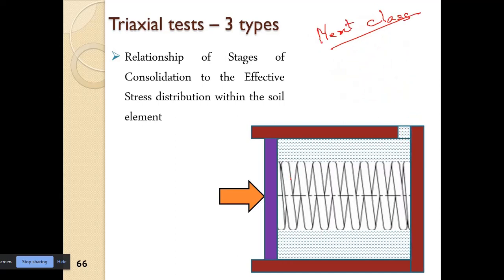Now what we do, we start from the first step again. We have the piston in the original position here. We have the spring in the free length position. So basically the compression in the spring x is equal to 0. We start from this position, so the force in the spring is equal to 0. And then we start applying incremental load in this case. Suppose we apply 1 kg, 2 kg, 3 kg and so on.